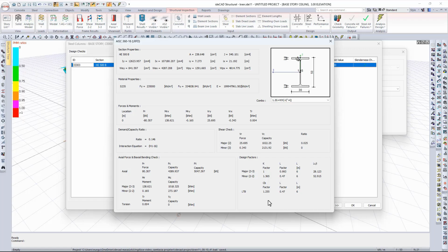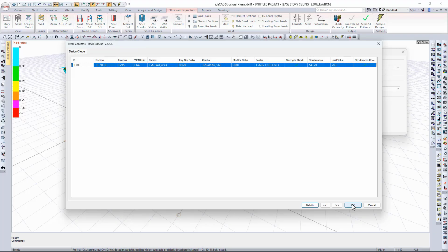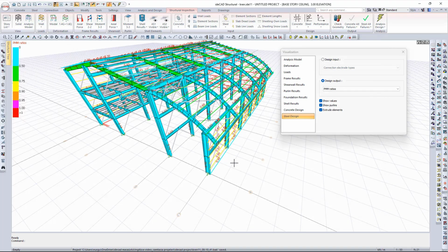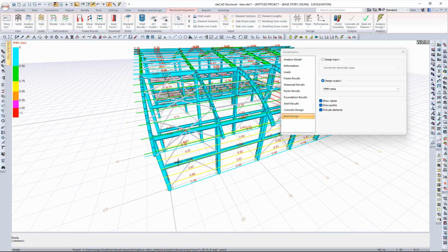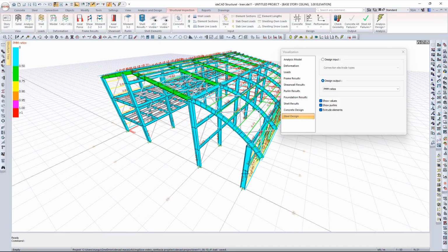If you recall, during the modeling stage, we mentioned that these parameters can be adjusted from the Design tab for each steel member, such as columns or beams. This window offers a comprehensive breakdown of all stability-related design inputs. Clicking the OK button will close this tab. Whenever you encounter a design failure or warning, you can return to this screen to investigate the root cause in detail.